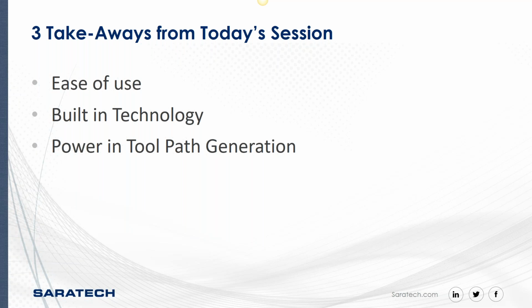And they're very powerful, and I have created toolpath with those and created physical parts, and you can control your surface finish. You can control and weed out chatter by using your percentage factors. And then the power in toolpath generation: just in NX12 alone, they've increased the toolpath generation speed by 50%. So between 9 and 10 it was 30%, and between 10 and 11, 20%, and now we're at 50%. So they've increased it each version by 10% or so. And we're very quick for the types of operations that we're creating toolpath for.